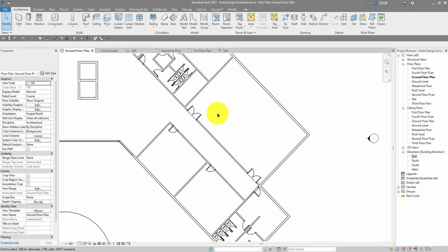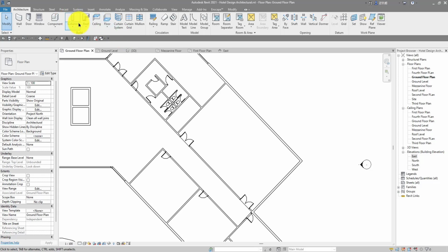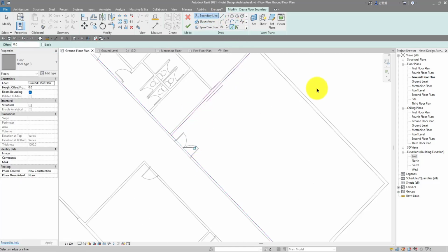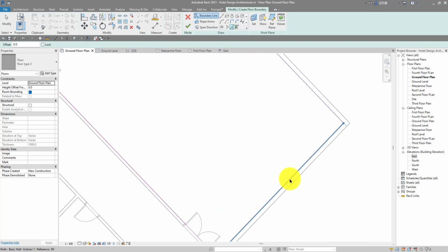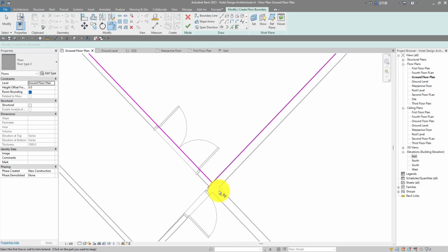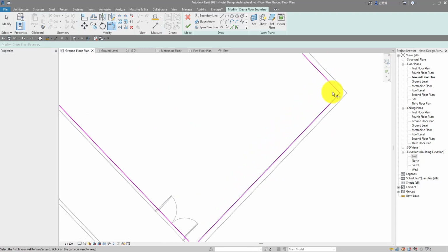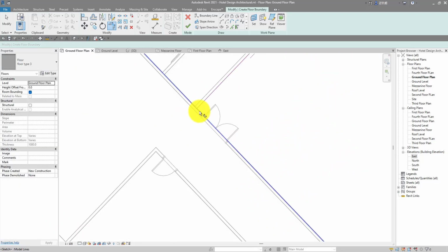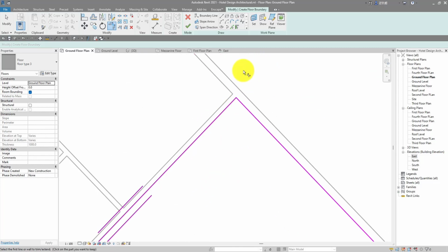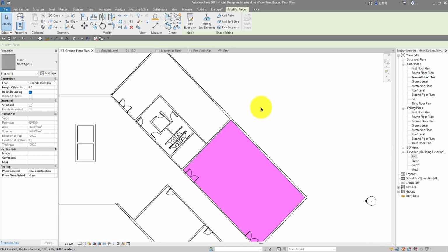So now I want to create the floor slab for this as well. So I'm going to use the same floor type finish 3. I'm going to use the pick line too. Pick that, pick that, pick that, pick this as well. Escape key a couple of times, TR on your keyboard to trim and extend. All right, trim with this, and also trim with that. Now hit on your finish. We have that in there.